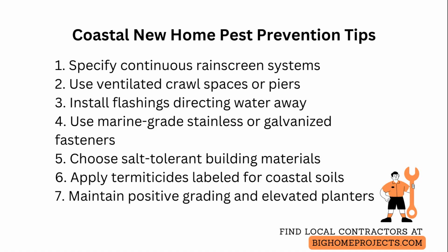For termiticide protection, select products labeled for use in coastal soils and apply according to label directions by a licensed applicator, treating around foundations and under slabs while ensuring proper bond to geotextile or gravel barriers where specified.